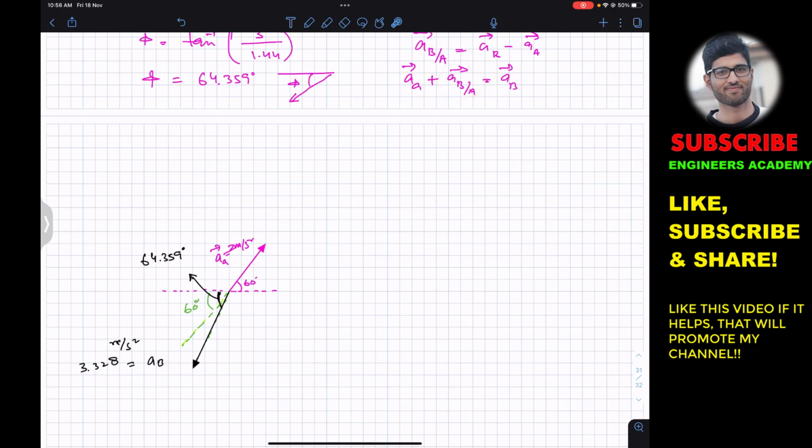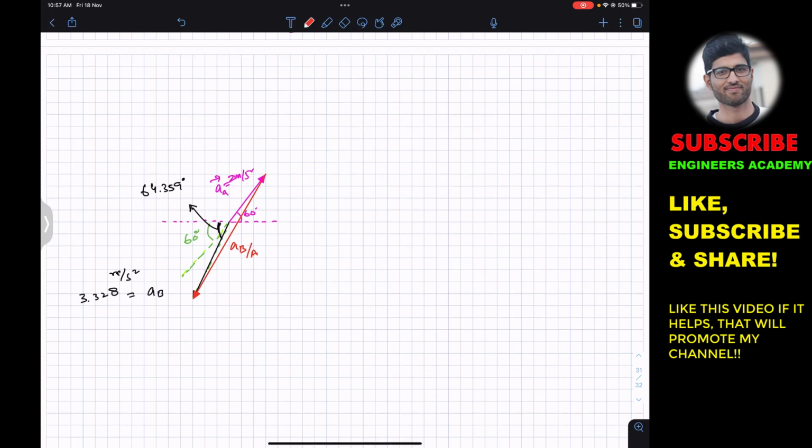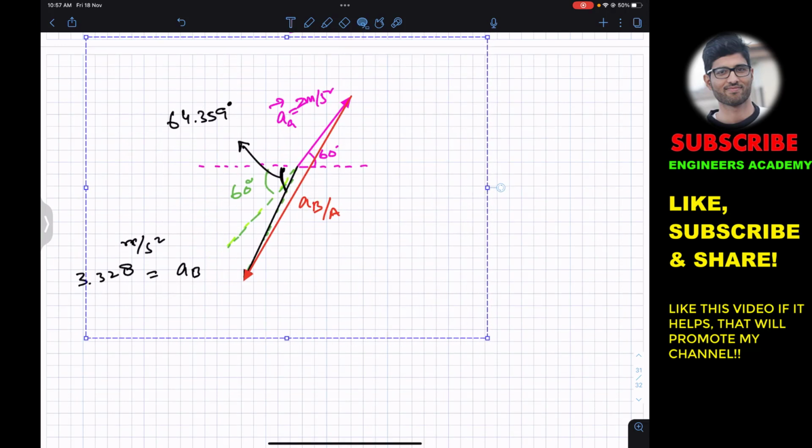So now we need to draw a vector which will start from the head of A and which will end on the head of B. So we need to add ABA vector with AA by head to tail rule. So AA, then this will be ABA from the head of this AA to the head of this AB. So this will be the acceleration of B relative to A. Let me make it a bit larger. This is the diagram, not up to the scale. So this is our diagram.